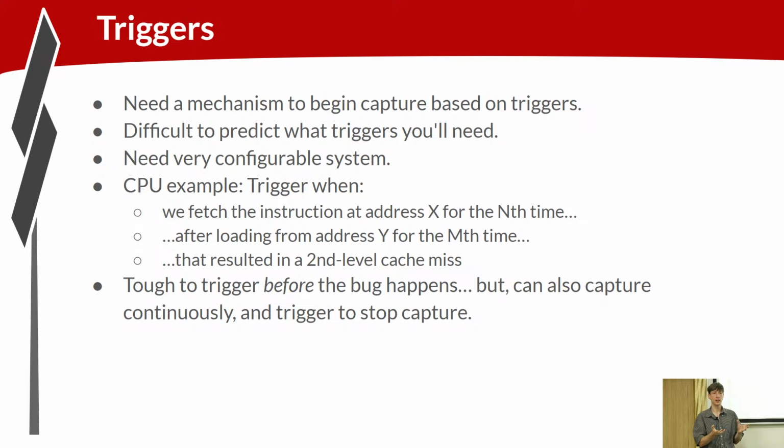So if you find that there's a bug that seems to relate to addresses that are on a 4K boundary, for example, you'd like to be able to configure your debug logic to trigger when it accesses a 4K boundary, right? So you build this network that is capable of, again, funneling in a bunch of potential triggers and then narrowing down on the ones that you think matter.